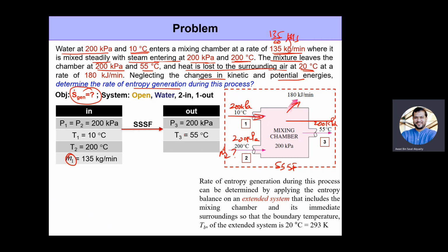Okay, so now let's go ahead and start by writing down the energy balance, sorry, the entropy balance equation. Okay, because let's figure out what we need here, right? So entropy coming in minus entropy out through heat and mass transfers plus the entropy generation should be equal to the rate of change of entropy within the control volume.